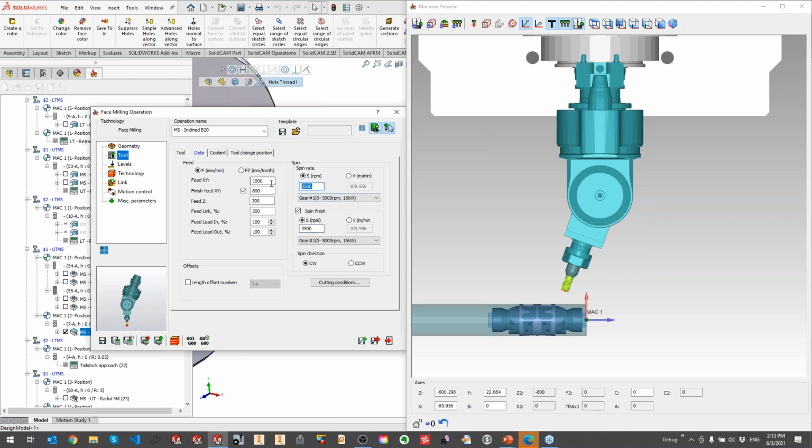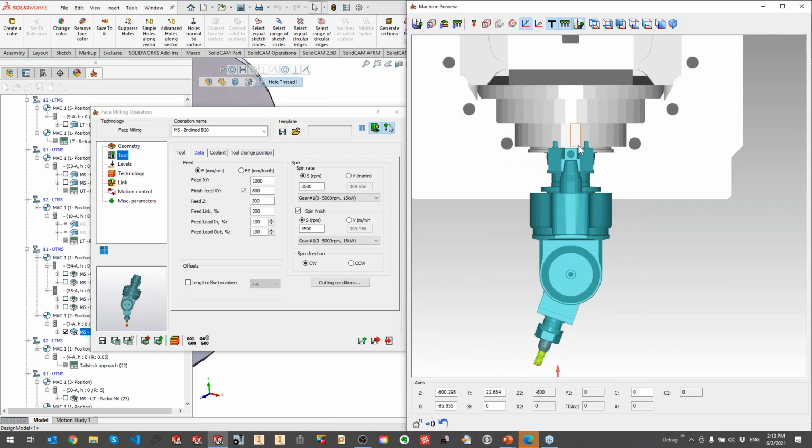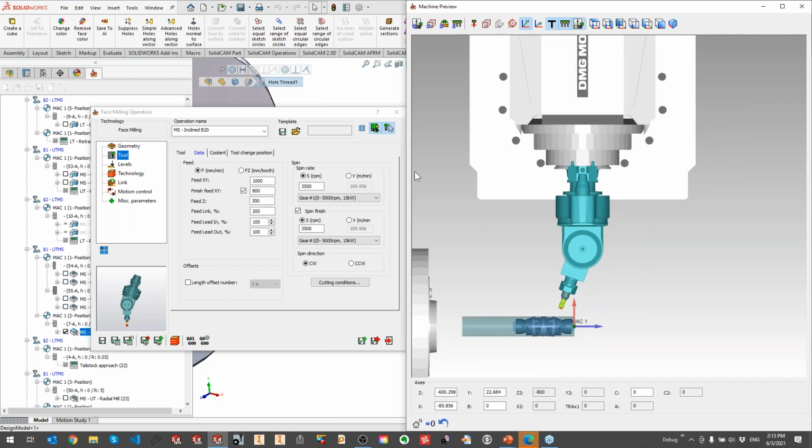As you can see, trying to define any value higher than 5,000, it will basically cancel that spin. But what this means for our drive unit defined on the turret. So I will leave it as 3,500. I'll just calculate. Actually, it is already calculated. So I'll just generate the G code.